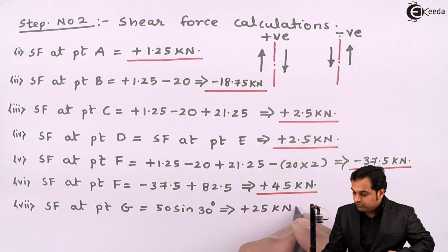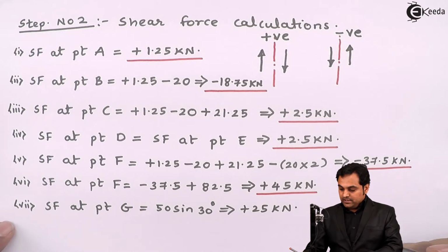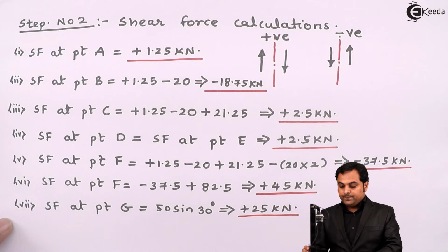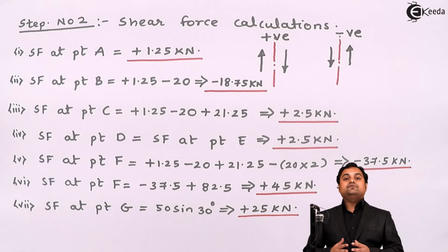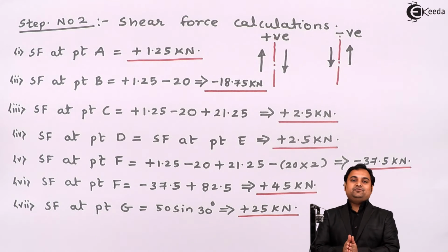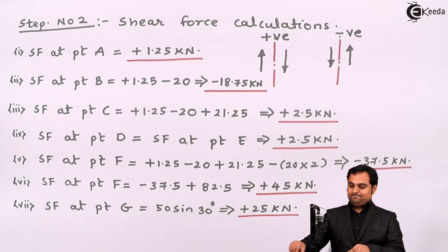So here I have found out the shear force values at each of the points. After getting these shear forces, we need to draw the shear force diagram, and for that I'll have to draw the beam again.